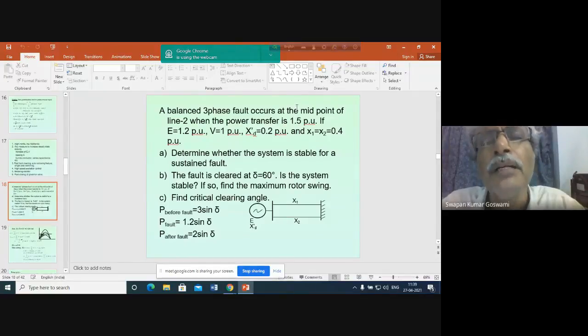But there is a sudden increase in current. So armature current increases, but armature flux does not increase because of the opposition. If you calculate inductance as flux linkage by current, flux linkage remains the same but current increases, so the inductance value calculated will be somewhat lower.